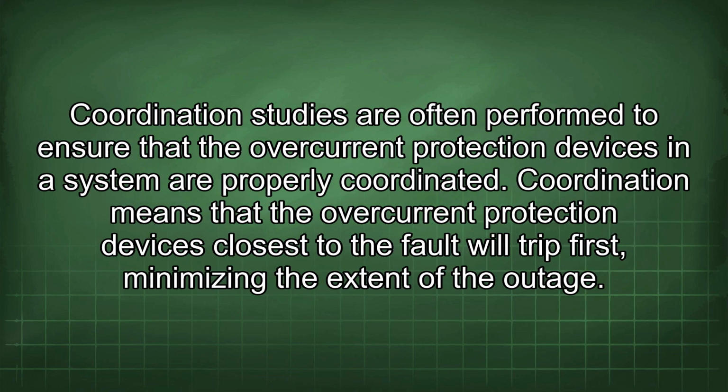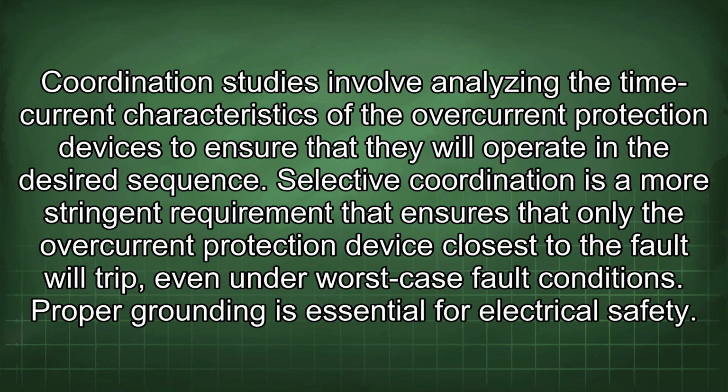Coordination studies are often performed to ensure that the overcurrent protection devices in a system are properly coordinated. Coordination means that the overcurrent protection devices closest to the fault will trip first, minimizing the extent of the outage. Coordination studies involve analyzing the time current characteristics of the overcurrent protection devices to ensure that they will operate in the desired sequence. Selective coordination is a more stringent requirement that ensures that only the overcurrent protection device closest to the fault will trip, even under worst-case fault conditions.